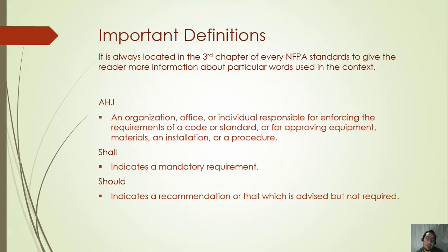And the other definitions that I want you to take care of, guys, are shall and should. What is the difference between these two? When we say shall, it's mandatory, guys. So whenever you see the word shall in standards, it's mandatory. It shall be provided by the designer. And should is just a recommendation. So you're not enforced to do a particular requirement if it's just a should or a recommendation.